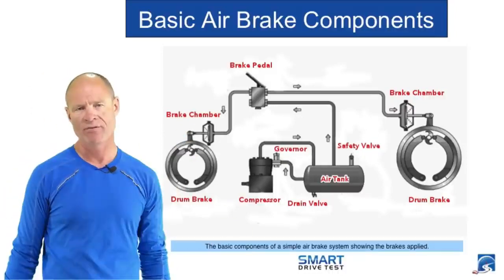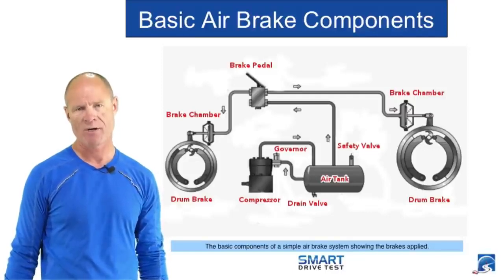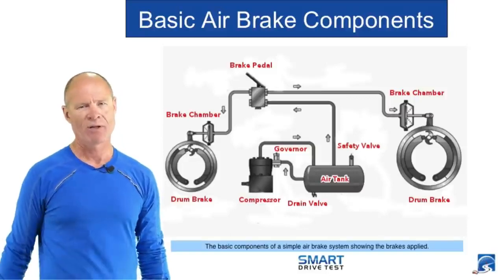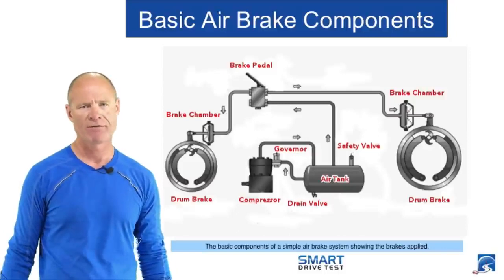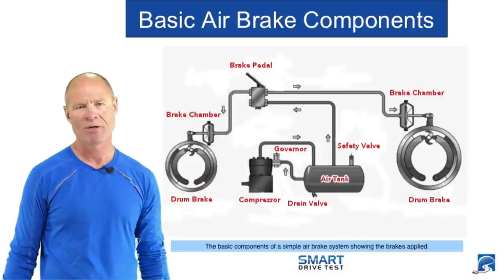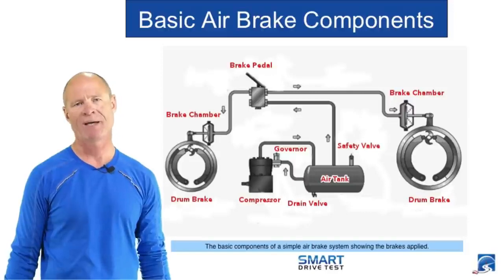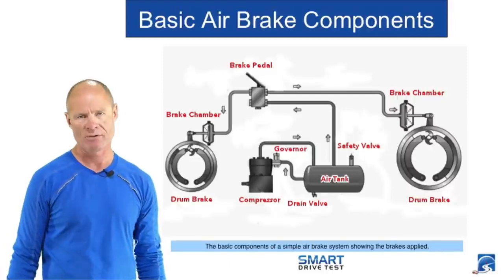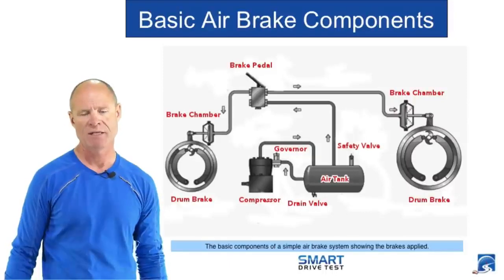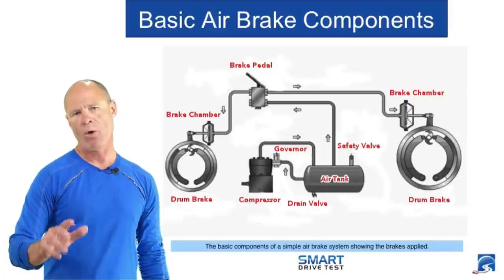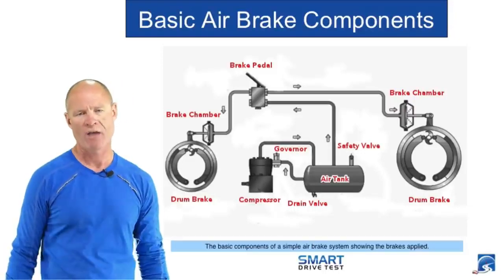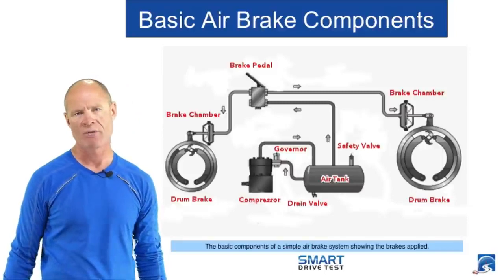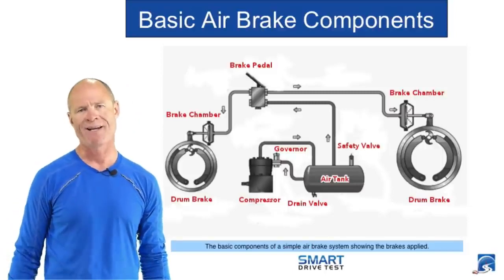There are 4 types of foundation brakes: drum brakes, disc brakes, air over hydraulic brakes, and to a certain extent, wedge brakes. Air over hydraulic brakes and wedge brakes, you're not going to find them in this day and age. They pretty much became obsolete when gasoline engines were replaced by diesel engines. Gasoline engines created vacuum, which made air over hydraulic brakes plausible because they could use the vacuum from the gasoline engine to power the master cylinder. Once diesel engines took over, they no longer created vacuum, and it was no longer feasible to have air over hydraulic. So air over hydraulic became obsolete, and they went to a completely air brake system.